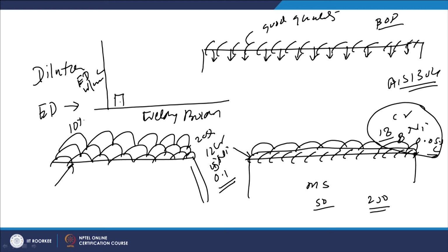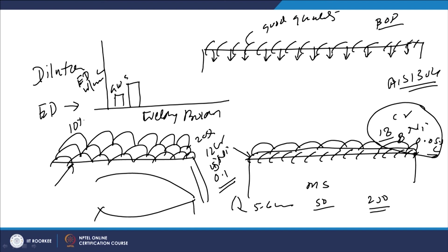So, gas welding offers the lowest energy density, because the flame is very wide and whatever energy is being transferred spreads over a larger area. So, energy density is less. While in the case of the arc, it is smaller in diameter, like 5-6 mm diameter of the arc at the bottom. So, energy density is high for a given set of parameters if we compare with gas welding. So, it offers the higher energy density for the shielded metal arc welding process.